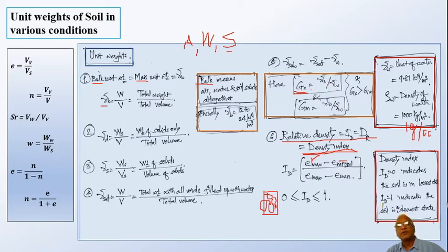So if you have the picture of the three-phase system in front of you, where you have solids, and then you've got air, and then water over here, then there is solids. Now in the denominator, the weight per meter cube of water is fixed. But G s, specific gravity of solids, is concerned with only solids and solids volume, whereas bulk means it consists of all this.